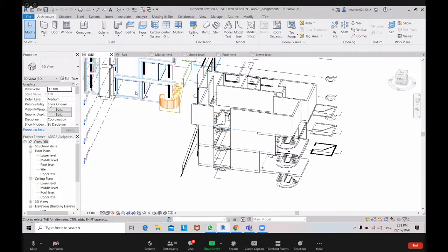You understand. You make the height. Make it unconnected here. Top constraint should be unconnected. And then you put a number. You make it 1, for example. Click OK. See, you see? It has become good now.